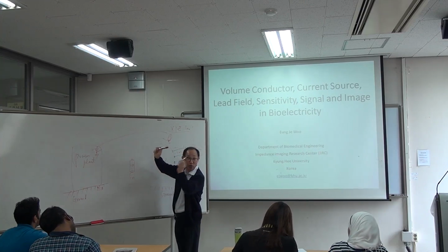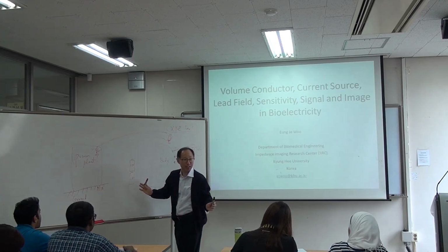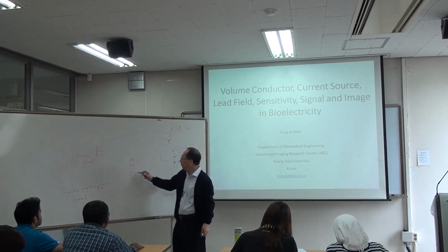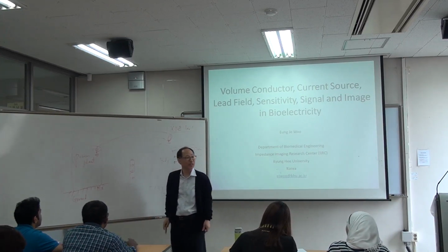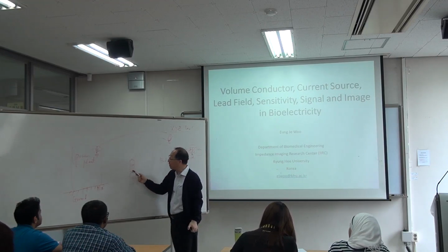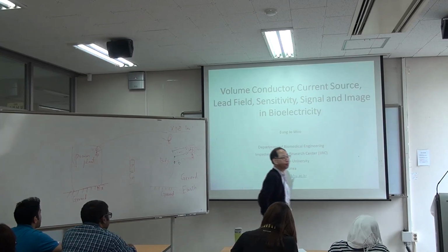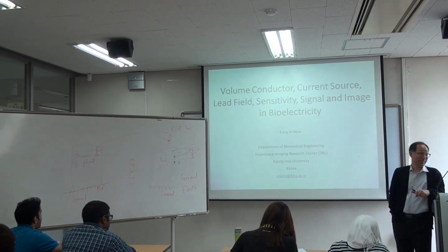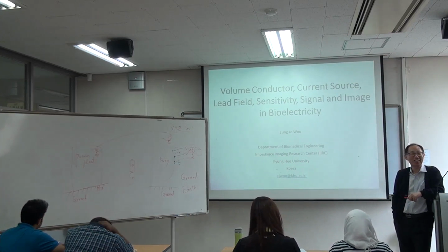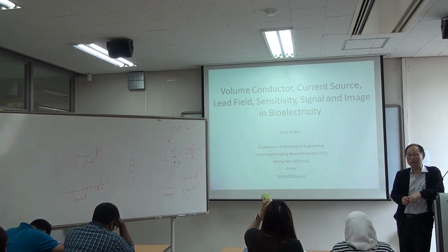If I change the reference point here, this is 1.5 volt, this is 3 volt. So the choice of voltage reference point is arbitrary. Once you choose it, that's the setting. If I connect this thing to Earth's ground, then I measure 1.5 volt, minus 1.5 volt. The only difference is this point is connected to the ground. That doesn't change anything. So this is a very common question and in some sense a confusion.